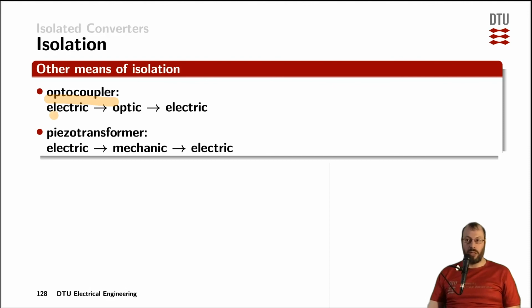So you can transfer the signal from electrical energy, for example, measuring through a current, an LED, have an optotransistor, so the light in between, and the base of the receiving bipolar transistor is controlled by the photons sent out from the other side and turns back into a current on the other side of the isolation barrier.